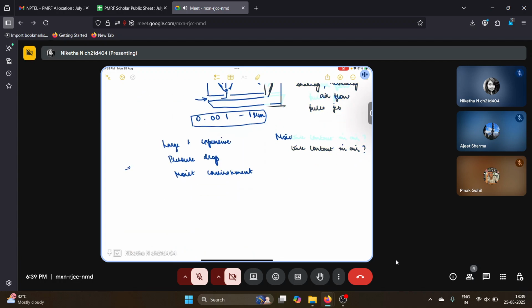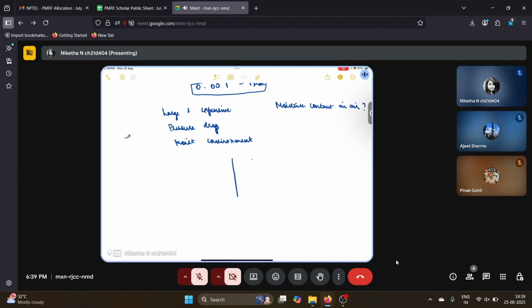What happens is, when you have a fabric filter like this and air is moving through, the air has water as well as dust particles. When this air flows out of the fabric filter, both the particles as well as the water will get trapped on the filter itself. When you have a lot of moisture, most of the pores will get blocked by the water itself.